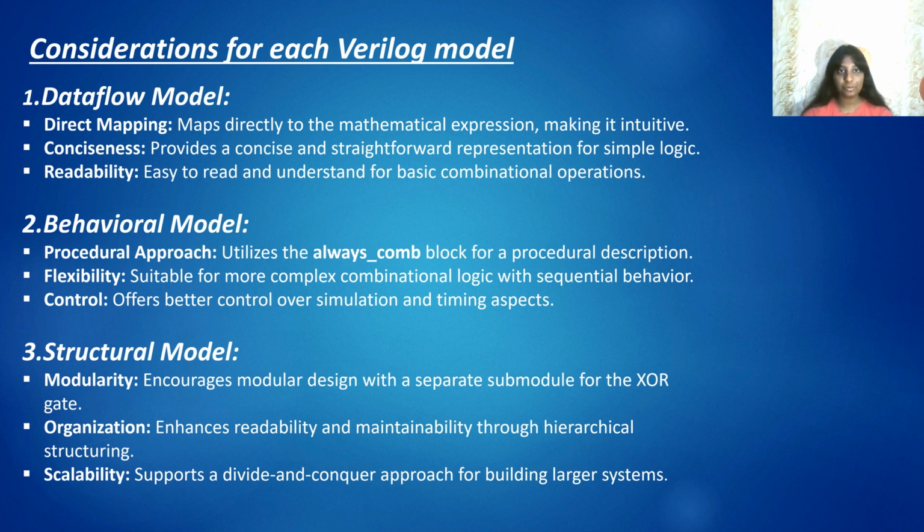Considerations for each Verilog model. First one is the data flow model. Direct mapping: it maps directly to the mathematical expression, making it intuitive. Conciseness: it provides a concise and straightforward representation for simple logic. Readability: easy to read and understand for basic combinational operation.